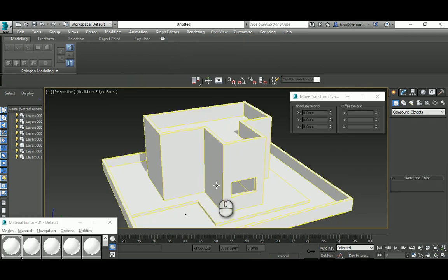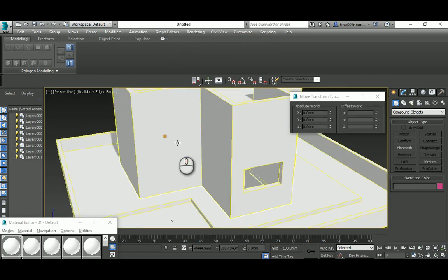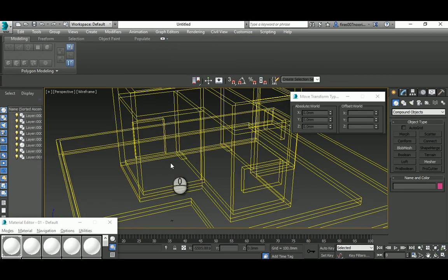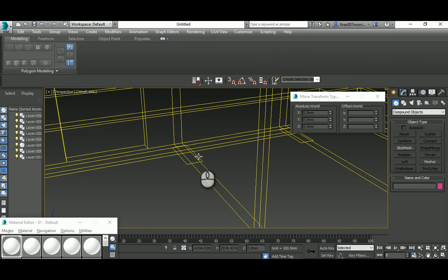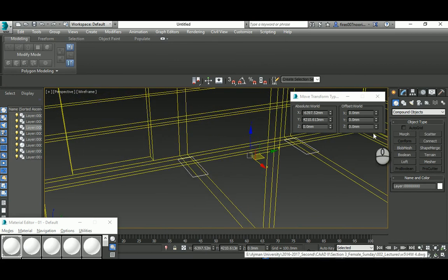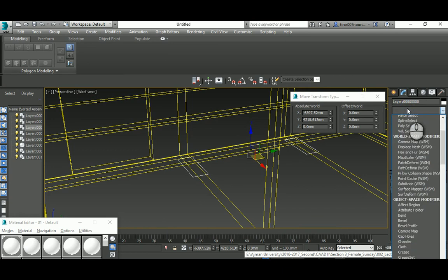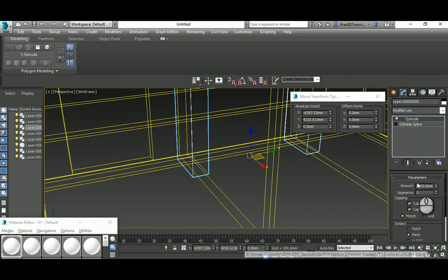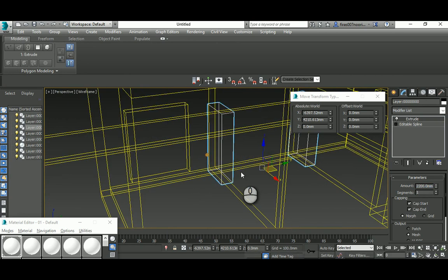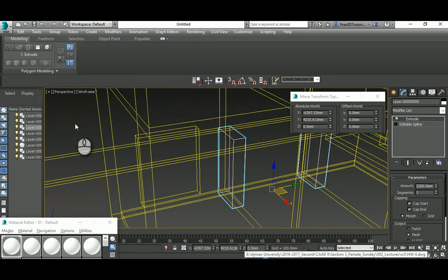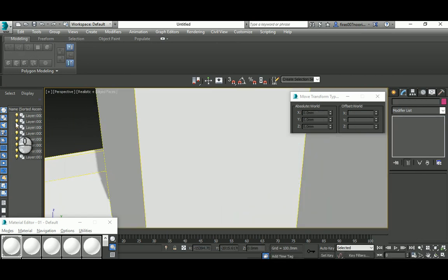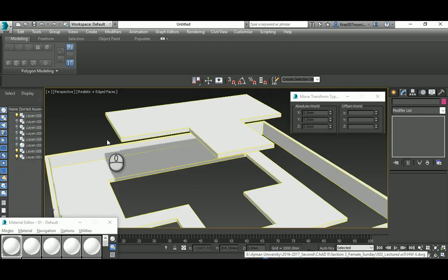If you don't see them, it's okay, just hit F3 or use those to hide whatever prevents you from seeing. Again, they are at 0, 0 and the extrude 2200. All doors are actually sitting on the floor finish. Now I don't see them, so F3, it's boring and hard to get them with material without seeing them, so let me turn off the whole thing.